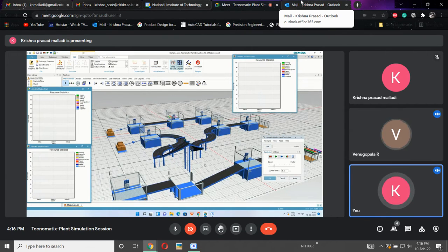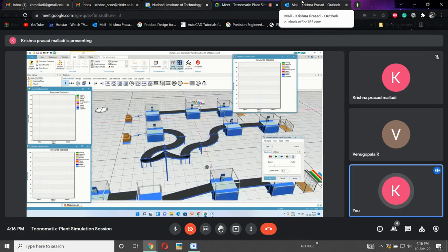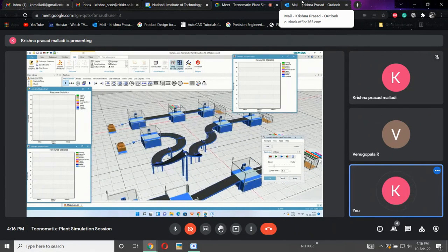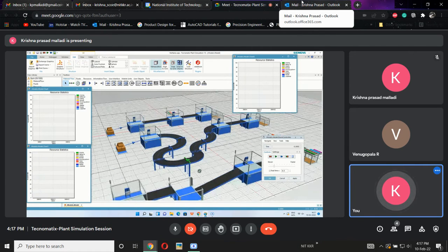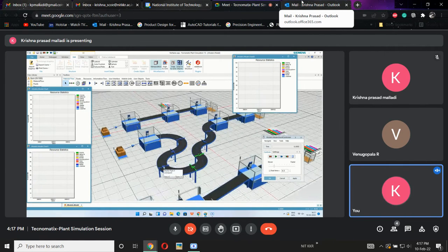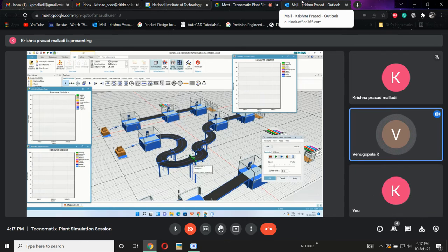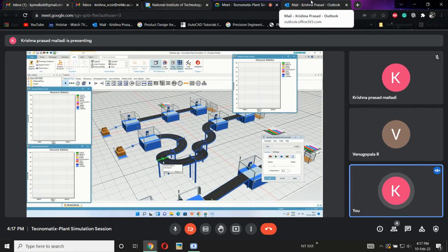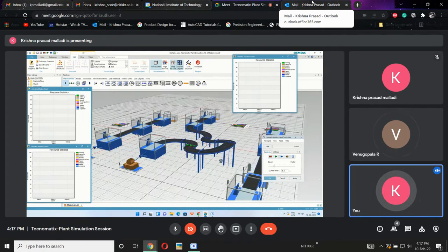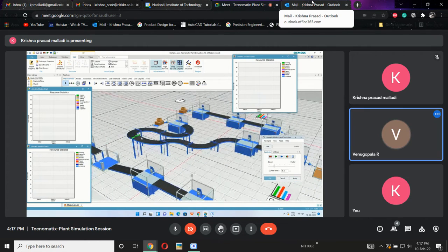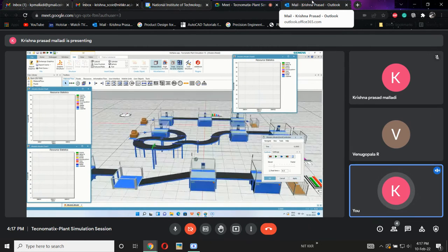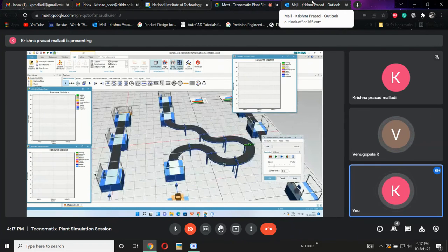But see, if I increase like this, which is in no way real, it is not at all correct. So I am holding it and decreasing this one. Once after attaining some height, I can hold Control and select multiple points, and increase the height, and at the same time the points will change simultaneously. Then only will we get a smooth increase in the height. Otherwise, a sharp edge will instantly be formed. Now see, at least it is possible.